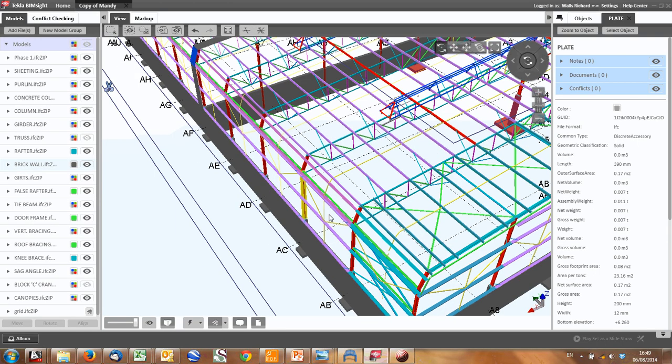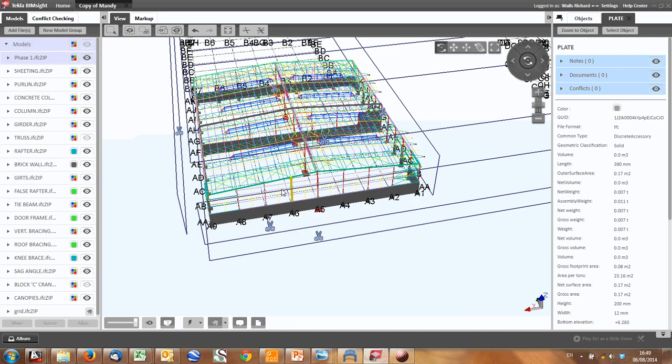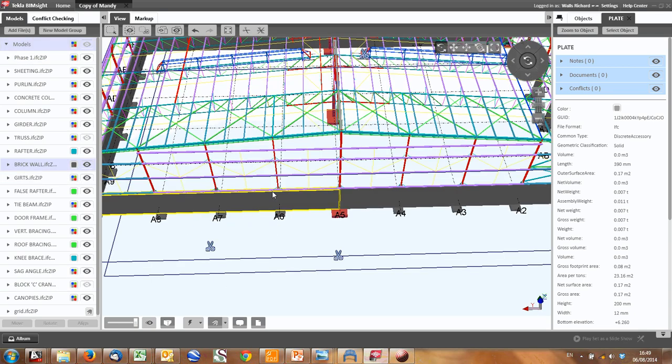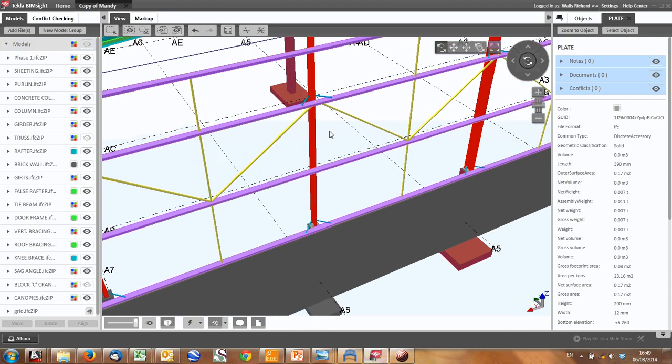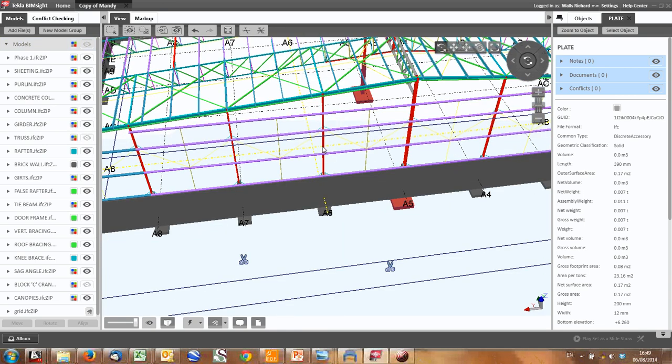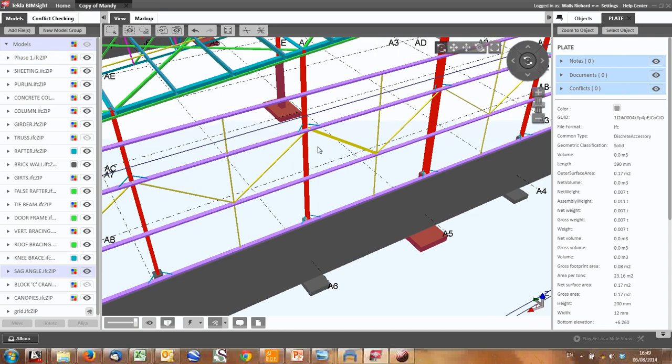So if we look at our model, wind load comes across the structure. But what happens if the wind blows from the other side? How are those loads taken? You can imagine, I can apply a little load here to the sheeting. How are those loads carried? Same question. Obviously, this goes up the sheeting and down the sheeting to our girts, from the girts to the column.